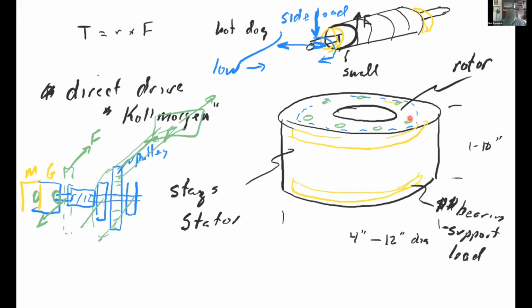Okay, let me just clarify that. When we're dealing with a system like this one over here, we get to control the motor itself, but along the way, there is windup, there is deflection, there's a spring right there. A coupler is a spring. There's another shaft and attachment point here. There's a belt. There's all sorts of springs in this system in order to make it really work. It's not a great way to do precision motion control.